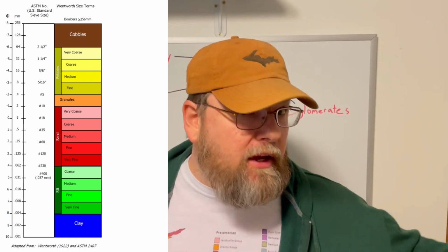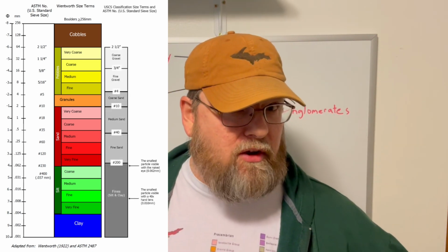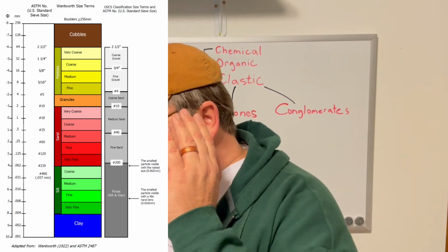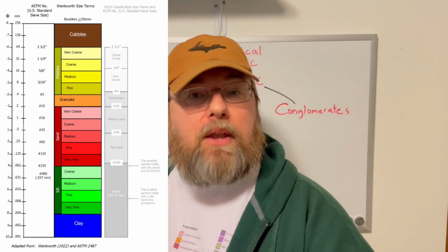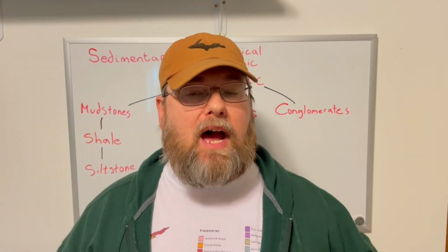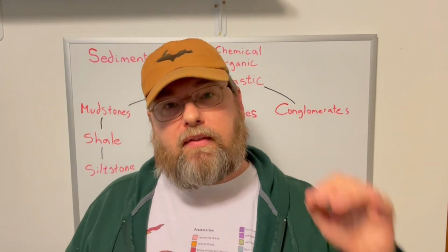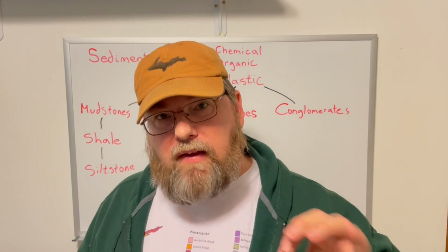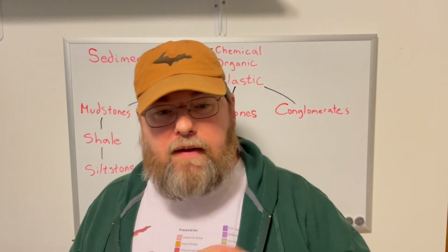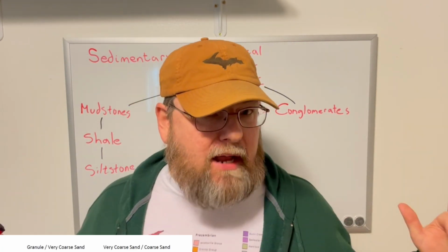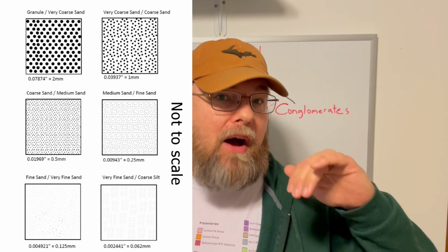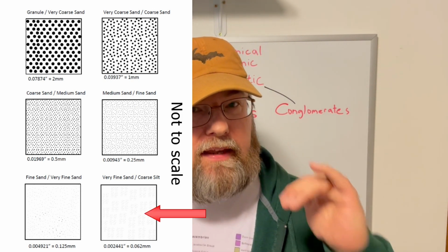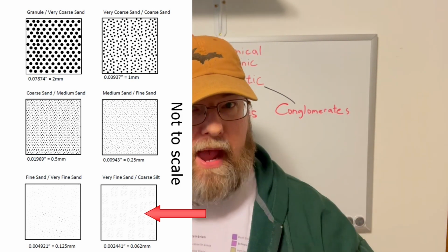And as geologists, we use the Wentworth scale. I am completely aware of the USCS and engineering scale. But in geology, we don't use it. Why do we use this Wentworth scale? Because it's a logical breakdown of clast sizes. They are by specific intervals, and a very fine sand at the very bottom of a sandstone is about the particle size that the naked eye can discern without magnification.